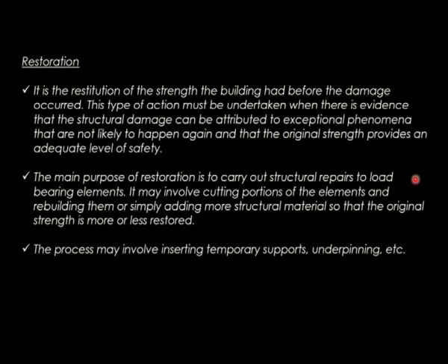Talking about restoration, it is a restitution of the strength the building had before the damage occurred. This type of action must be undertaken when there is evidence that the structural damage can be attributed to exceptional phenomena that are not likely to happen again and again, and that the original strength provides an adequate level of safety.